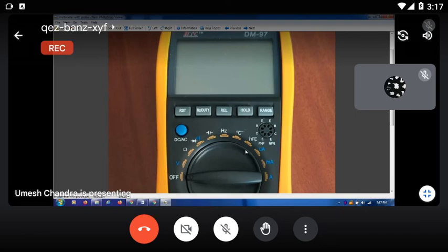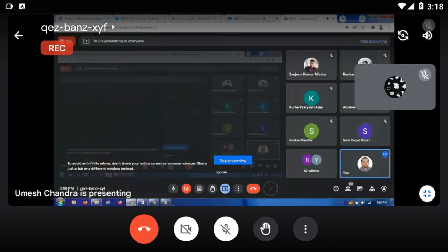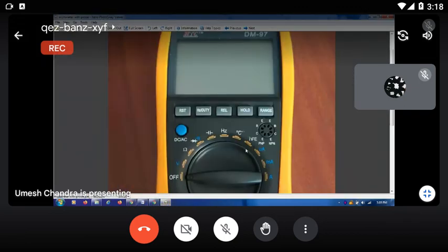First identify whether the transistor is NPN or PNP. Then after that you identify the pins: emitter, base, and collector. Okay. Then you mark here, it is already written C, B, E. Again, PNP and NPN: first you identify NPN or PNP, then the emitter, base, collector of the transistor. If your transistor is NPN, and you have identified emitter, base, collector, then you go to the NPN side, where B means base, C means collector, E means emitter. Just fix the BCE points,